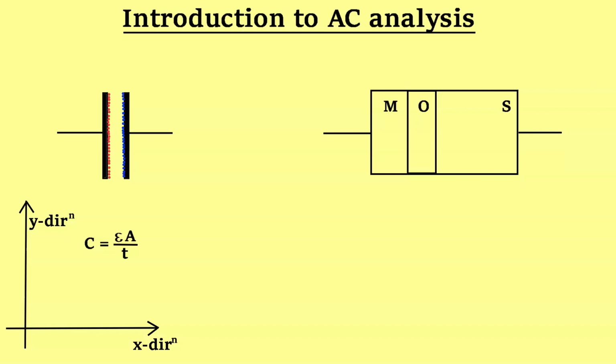First, consider a normal capacitor in which charges are deposited exactly at the surface, and these charges exert repulsion force on each other. But since all the charges are at surface, the force will be in the y direction. Now consider a MOS capacitor. On the semiconductor side, particularly in depletion and inversion region, charges, since occupying space in x direction also, they exert repulsion force in x direction also, which reduces the charge holding capacity or capacitance of the capacitor.